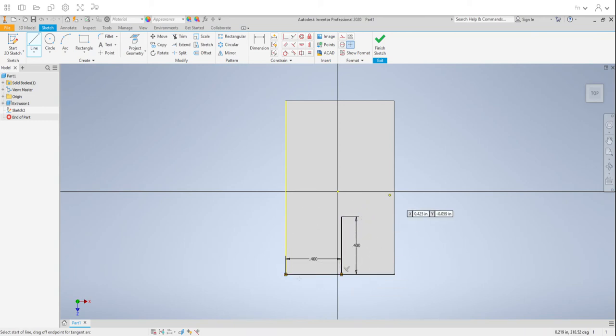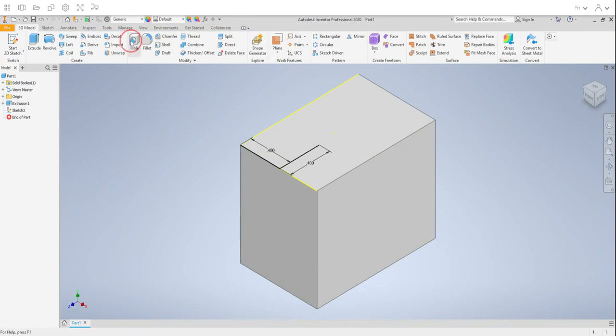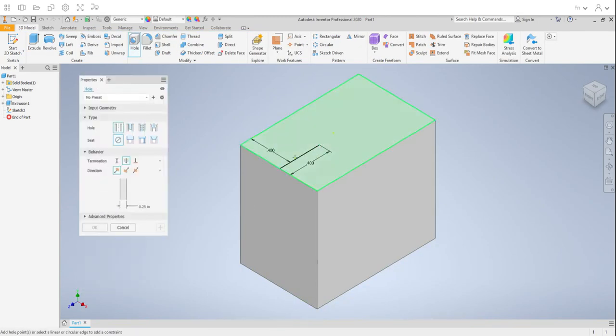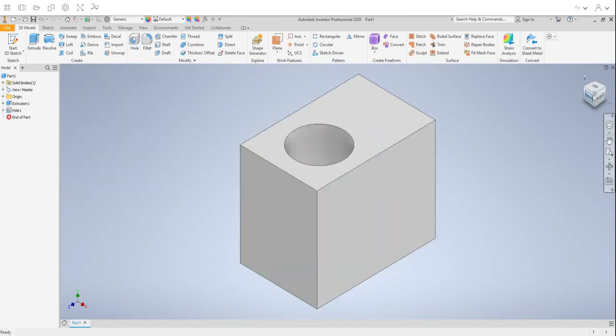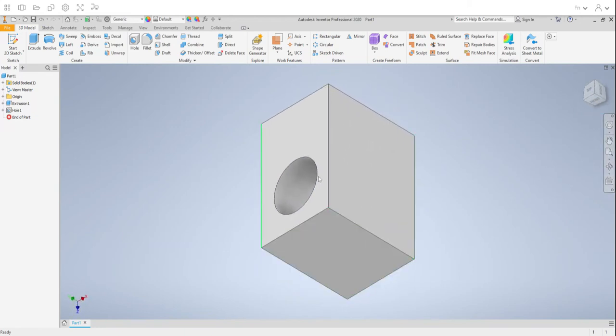If I'm drawing these lines, I'm not going to extrude these lines or use them to actually draw a physical feature. What I have now, though, is a point of reference that I can use when I select the hole feature. And so I can place the hole right at the end of those lines, and now I know the location of this hole is exactly where I want it. The most basic version of the hole tool just gives you the option to set the diameter. And so I could set that and then be done, and that creates a similar effect to how we started at the beginning.